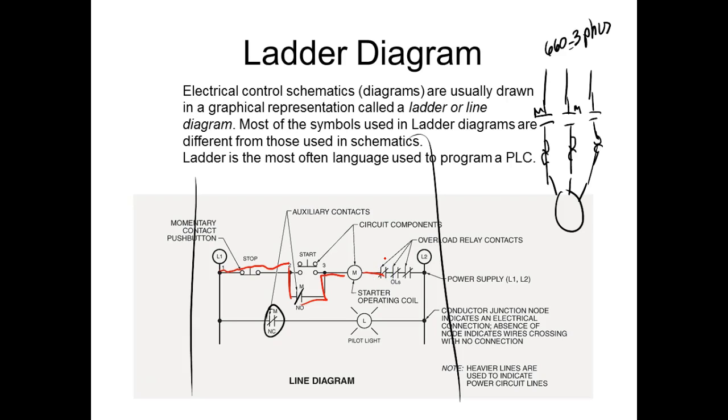So all I did was hit a little green button over here that says start. I hit the button, I let it go, and the motor turns on. And it stays on because we seal it in, right? You understand? This is called a seal-in circuit. It's called a memory circuit. This is a very popular circuit because it allows me to use a push button to control a relay instead of using a switch.